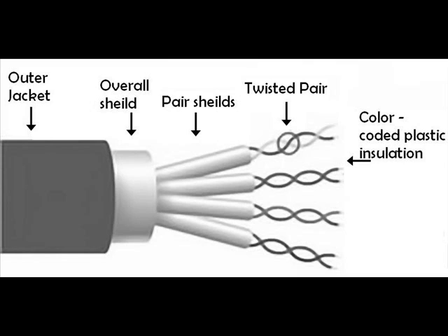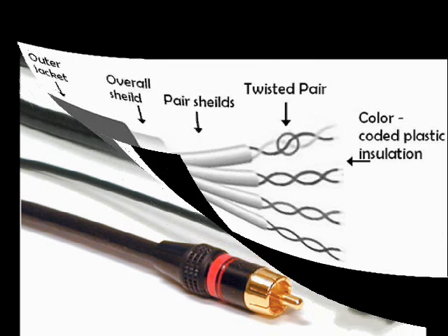Still can be used same as UTP without any need of rewiring buildings. After all, STP is still reasonably cheap. Difficult to install, as metallic shielding has to be properly grounded at both ends to prevent it from acting like an antenna. Because of an extra cost and installation difficulties, it is rarely used in the Ethernet networks.